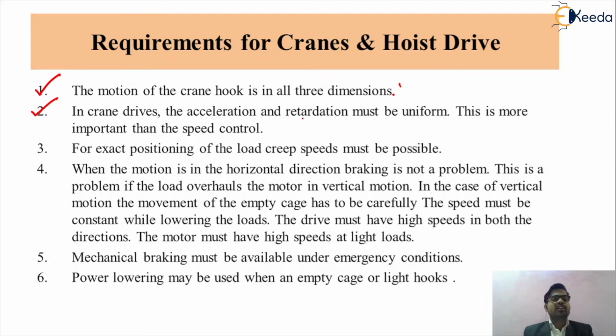This is more important than the speed control, because friends, while we are using a crane, we have to lift a load and just put the load. So we have to get various types of accelerations, because we have to move that particular load in a particular direction, and while we are putting that load at a particular site, we will require a retardation. So while we are using a drive for cranes and hoists, we have to take a very important point into consideration. This is called acceleration and retardation, in spite of the speed control.